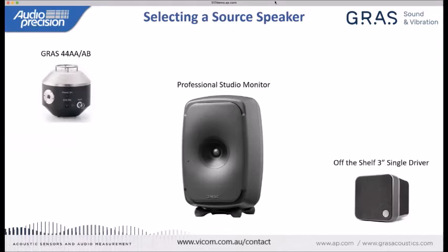The next question is going to be, what do we use as a speaker to generate the actual acoustic signal that we want to use to test these microphones? This is sort of an array of choices, no pun intended. I'll say that the first choice, especially if we're looking at microphones that we want to evaluate for use in voice applications, is a mouth simulator.